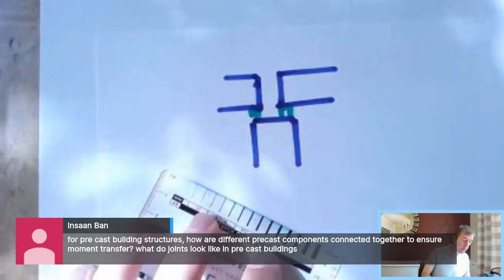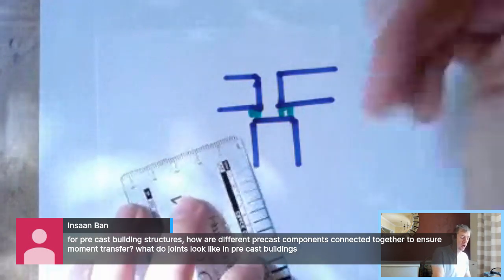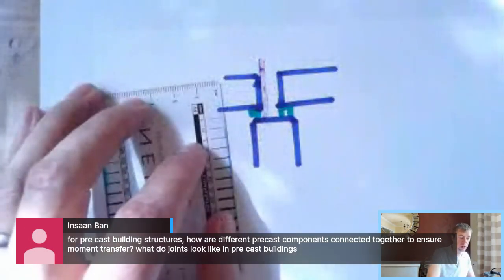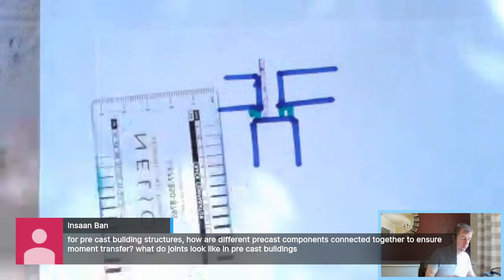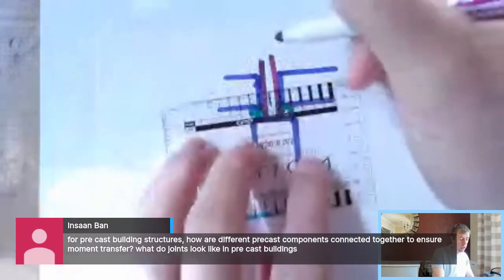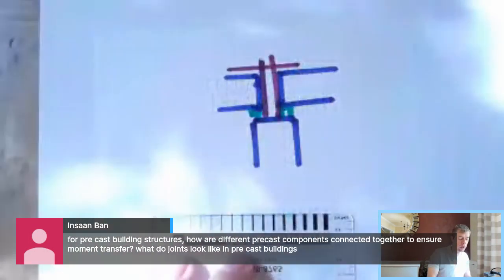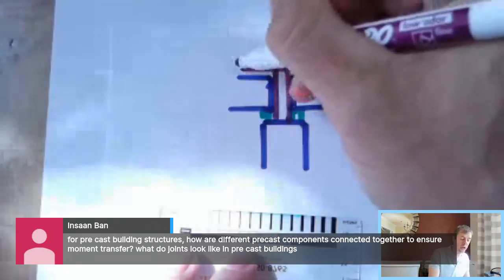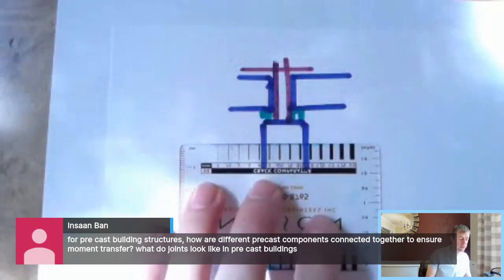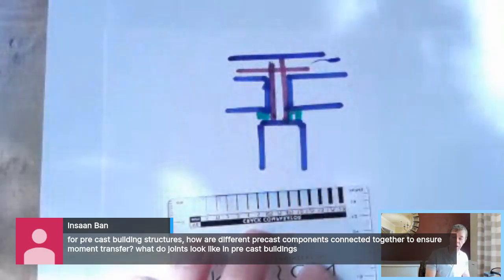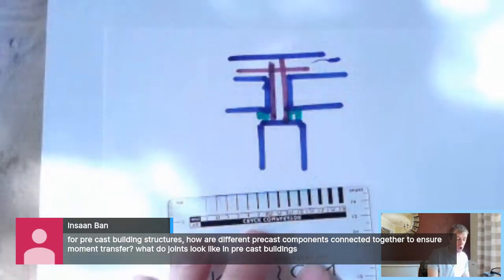So what's going to happen here is that you're going to take your rebar out of your column rebar. Rebar's not helping me here today. We'll try this picture, see if this is a little bit better. Rebar. You may tie another set of rebar here in the topping slab, and then you're going to cast all of that in concrete. All of that joint is going to go cast in concrete. So when you fill in the deck, when you fill in the topping slab up here, you'll fill in this and this and this, all of it together to create one strong connection.